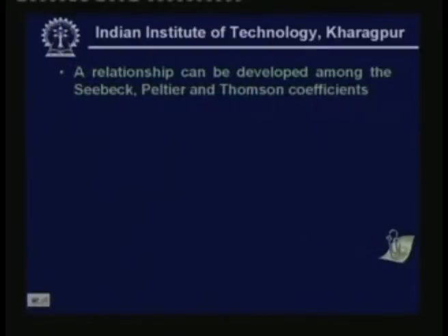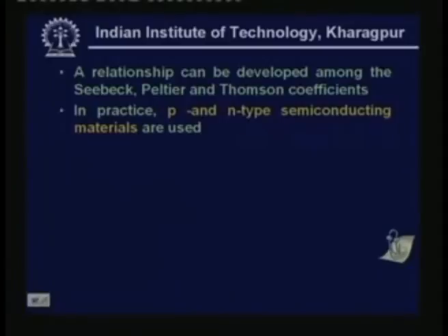So it can be easily shown that a relationship exists between the Seebeck, Peltier and Thomson coefficients. And in practice we do not use pure metals because pure metals have high thermal conductivity, which is not desirable. What we require is a material having high electrical conductivity but low thermal conductivity. So metals are not used, we use P and N type semiconductor materials in actual thermoelectric refrigerant